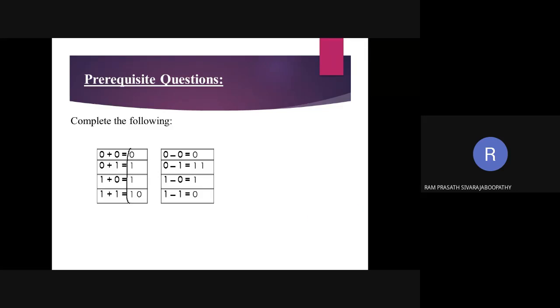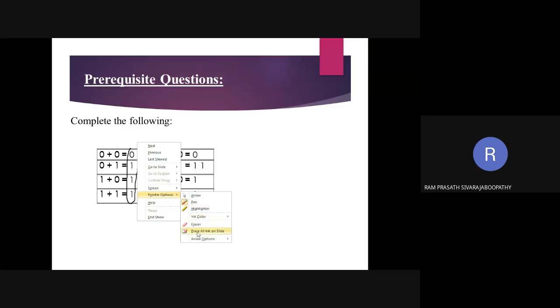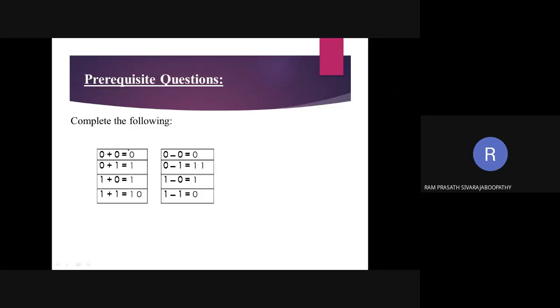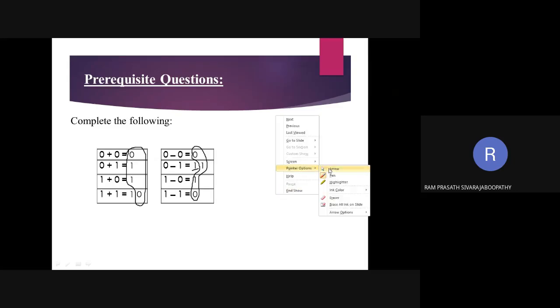So here it is termed as sum. The alignment has changed here. Sorry. Wait a minute. Here it is considered as sum. This is sum. Okay. So if you look here, here it is considered as difference. Clear? In both, what have I got? 0, 1, 1, 0. Here also 0, 1, 1, 0. When do I get carry 1 here? For 1 plus 1. Here, 0 minus 1 gives a borrow. That's the difference. Fine? Okay.